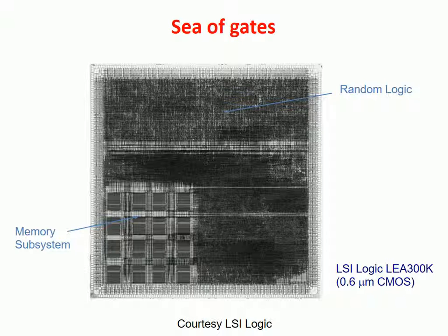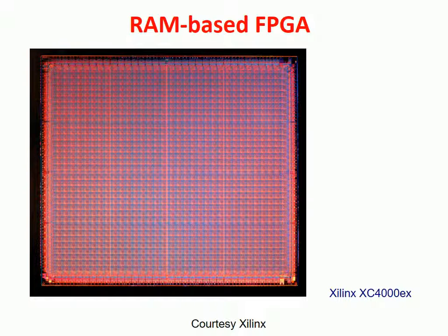These are just two pictures, just two examples of what I've shown. This is a gate array-based chip. You see the underlying structure is extremely regular. Then on top of it we have the interconnections that are the only part that has been designed. Okay, so only this interconnection part is designed and obtained in the fabrication phase by only fabricating the interconnections. This more regular part is a memory subsystem that, of course, becomes much more regular because as usual, it is an array. Everything is identical. Also, interconnections are not random.